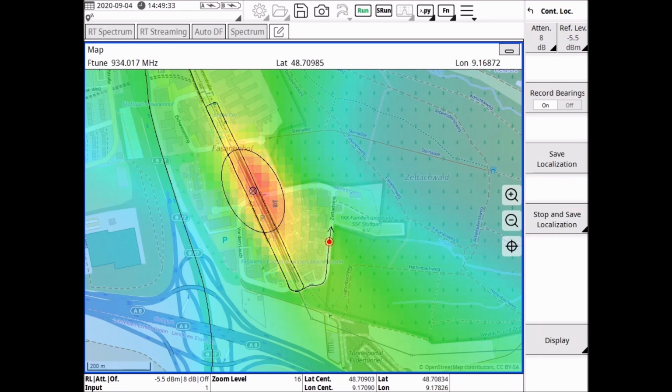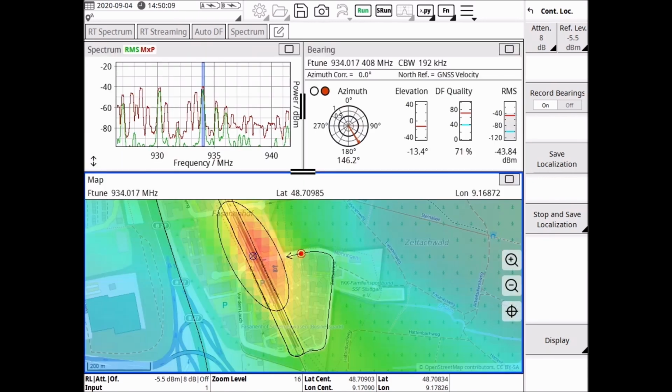For techies, it is essential to understand that the antenna's correlative interferometer principle evaluates the azimuth and elevation angles based on one and the same three-dimensional covariance vector, which will be correlated to the reference database with its permanently stored 3D calibration data. Hence, next to the azimuth angle, the elevation angle too is the result of a traceable mathematical process which is actively taken into account for direction finding.